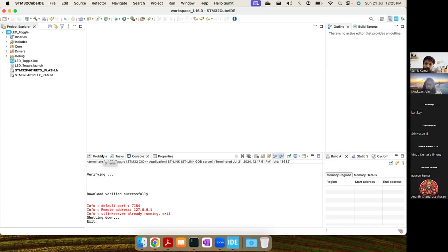The need of pull up, pull down resistor. There are three states which we have. First is the on state, which is basically the high state, then the off state, which is basically the low state, and there is the high Z state, which is called infinite resistance. Say there is VCC and there is ground, and between them we are not connecting anything to the pin.